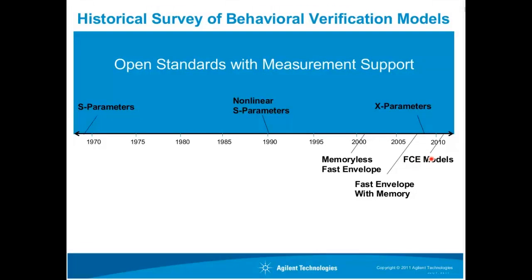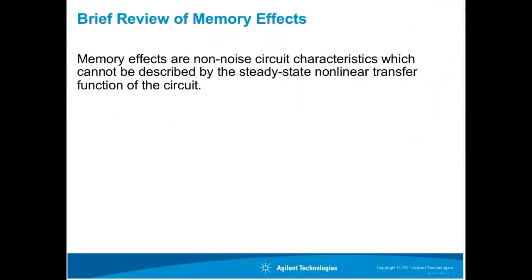So let's take a look at memory effects for a little bit. We'll review some of the slides that were presented in February, and then we'll come back and take a closer look at this flow. So just by way of definition, I'm going to define memory effects as non-noise circuit characteristics which cannot be described by the steady-state nonlinear transfer function of the circuit.